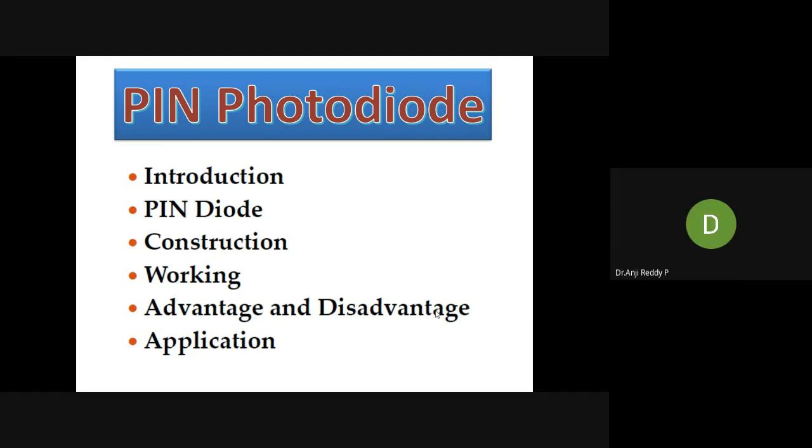Maximum. Which is maximum, current or voltage? Voltage. Right. What about the current at open circuit voltage? 0. Right. What about power at open circuit voltage? 0. Right, good. And where will we get the maximum power point?